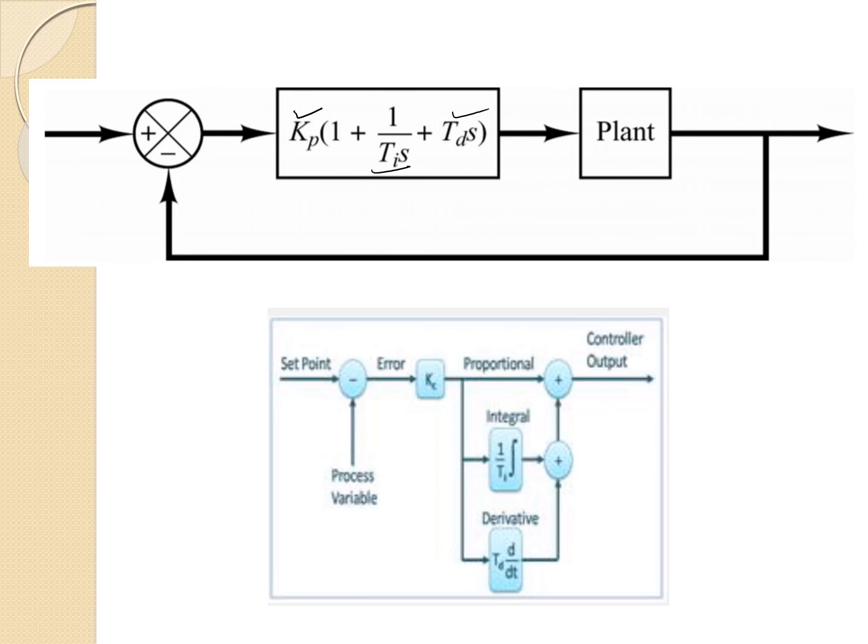So if the controller uses all this kind of PID controller, then there is a value for this Kp, a value for this Ti, and there is a value for this Td. So if you want to use only P, there is no value input for the other ones. Only the controller setting for this one is input to the controller system.